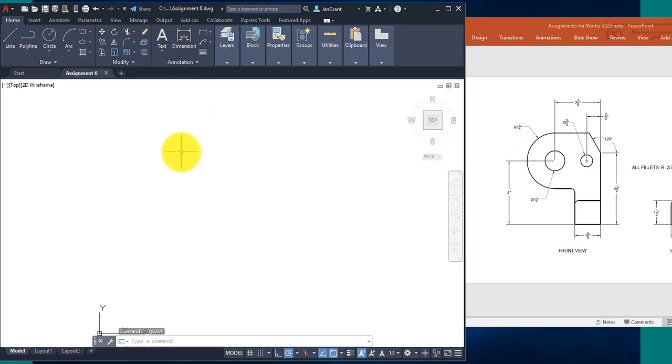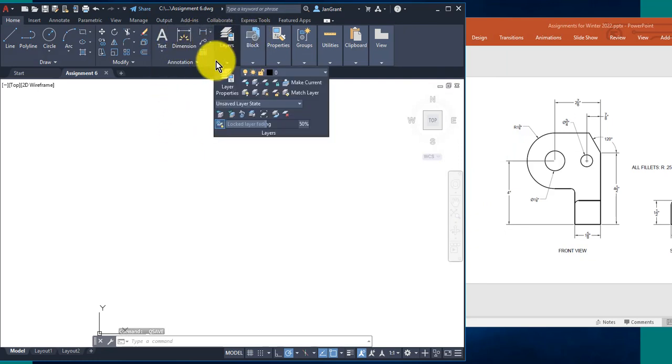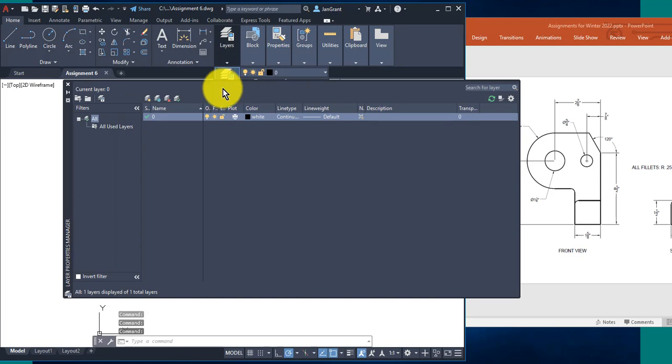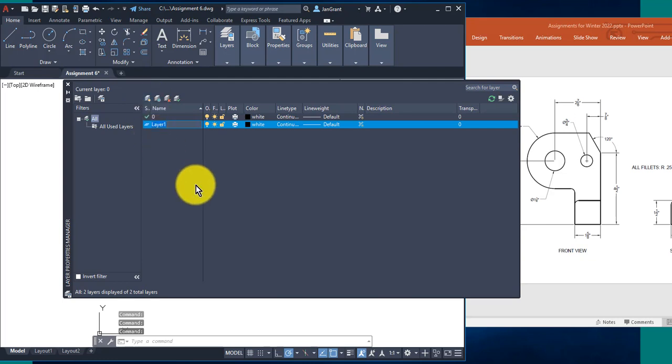So here we want to go to layers and layer properties. My screen is condensed a little bit more, so the layers panel is probably showing in yours. And here I only have just kind of a small box, so you know to go to layer properties and click on here the stack of papers right there, the icon for creating a new layer.